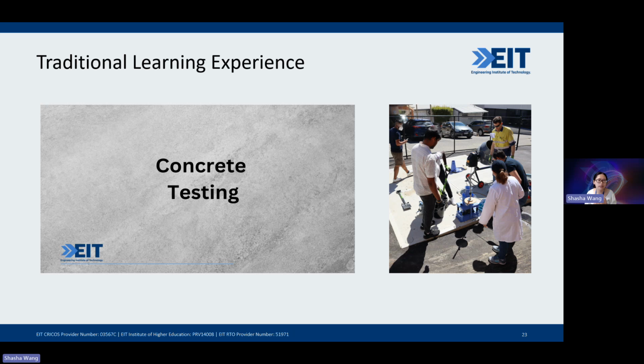So this is a video cast by Dr. Igor and Dr. Anna. We actually tested concrete. This is the load history of the testing. We tested the 28-day strength of hardened concrete based on standard cylinders with a diameter of 100 mm and a height of 200 mm. So these are just some of the examples that we did in our lab.